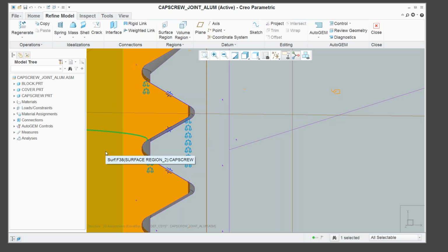If you're doing it with surfaces, the same procedure, you pick surfaces, but even better than that is just picking bodies. I just pick a whole part and say, here, we'll take this whole screw and we'll contact it with the piece below, and we're good to go. And I don't know if it would work here, but it works in relatively simple cases pretty nicely. And in fact, there are some advantages to it. So that's pretty much all you've got to do.